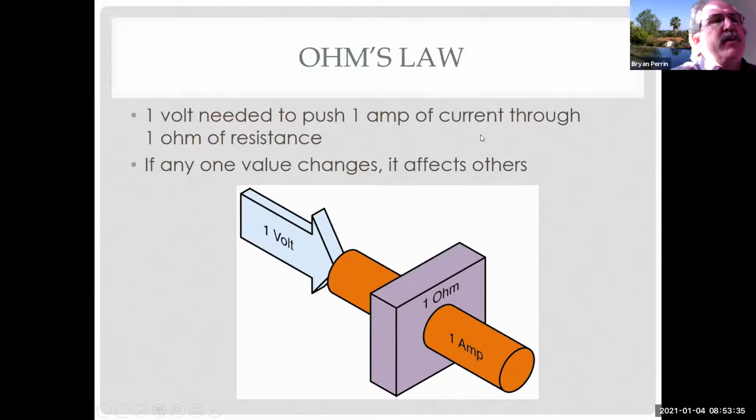That's also why we see systems using more voltage. So cars have not always used 12 volts. In the mid-1950s, we went from 6-volt vehicles to 12-volt vehicles because a 12-volt vehicle can flow twice the current through the same amount of restriction, right? Because it has twice the pressure, which means what? I can run smaller cables. It lightened cars up, made it cheaper, made it much more reliable.